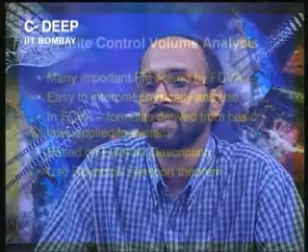Many of the important fluid mechanics problems we can solve using this finite control volume. We are just defining a control volume, and then what happens to that control volume is what we are analyzing. Many of the fluid dynamics problems we can analyze using finite control volume analysis. This analysis is much easier to interpret physically, and we can easily use this concept since it is simple to interpret, and the formulas derived from basic laws we can apply directly to the system.